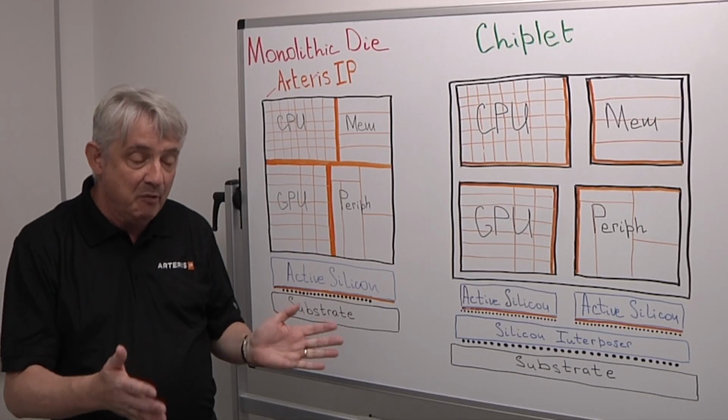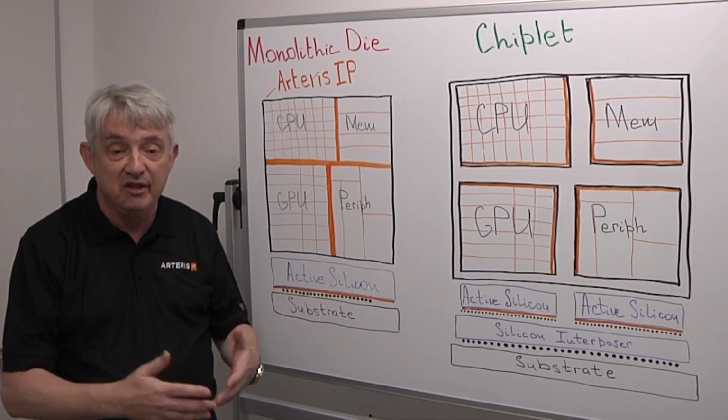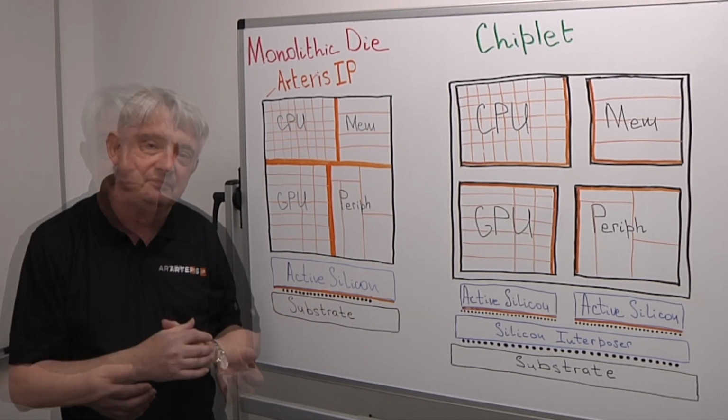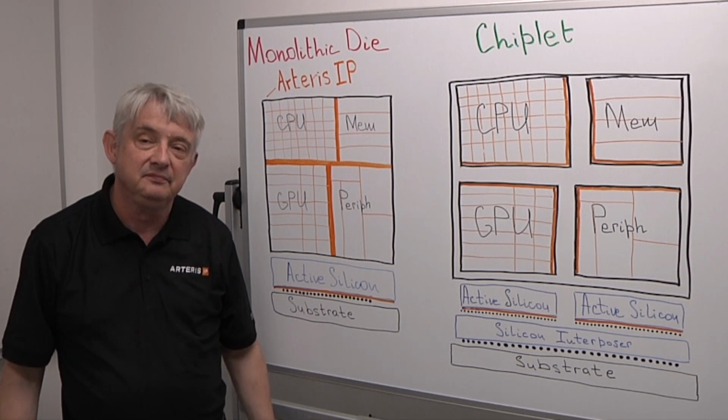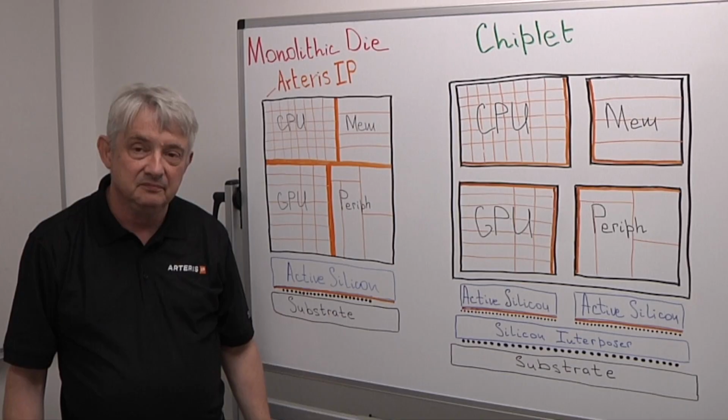So typically, people might use just one UCIe interface, but there's no reason why you can't have more. So you could have, for example, 2 or 4 UCIe interfaces to increase that bandwidth. One of the advantages of moving to an advanced package is that you don't necessarily need exactly the same type of device. You can have heterogeneous types of dies too, right?